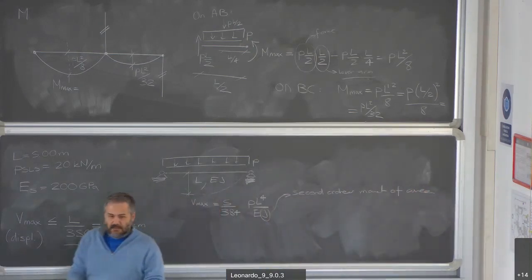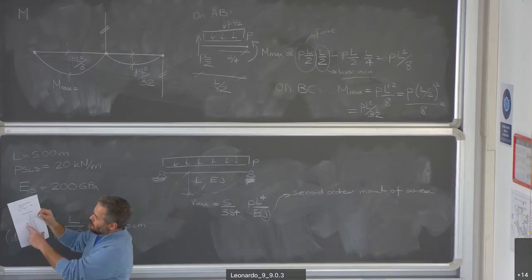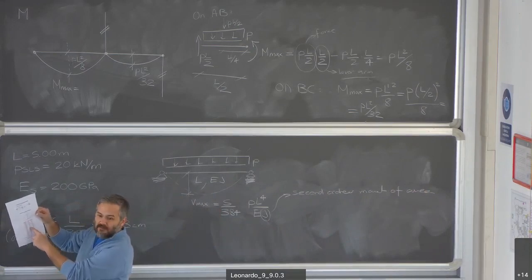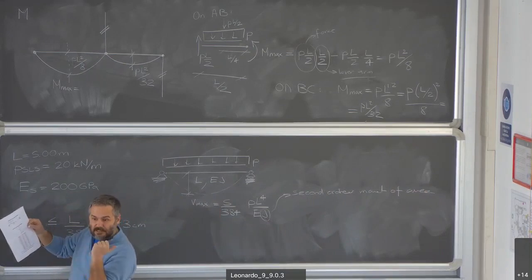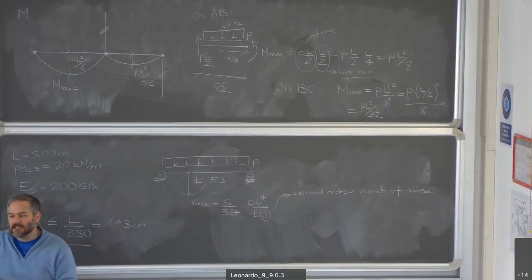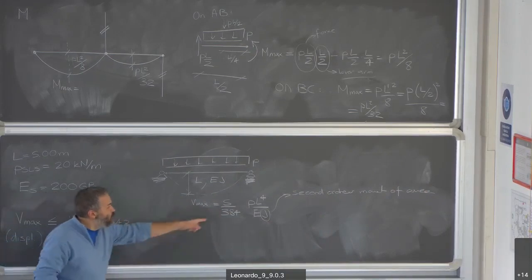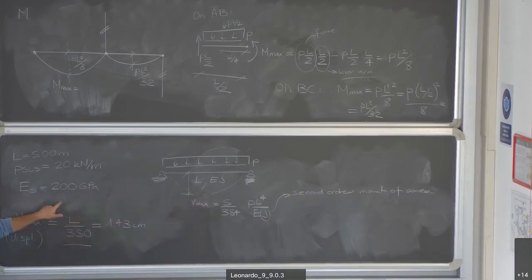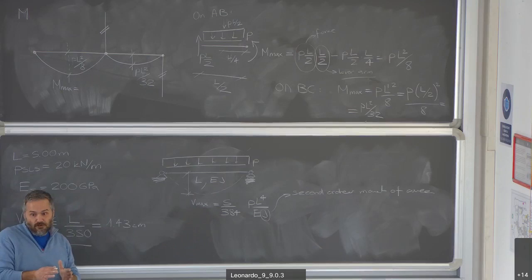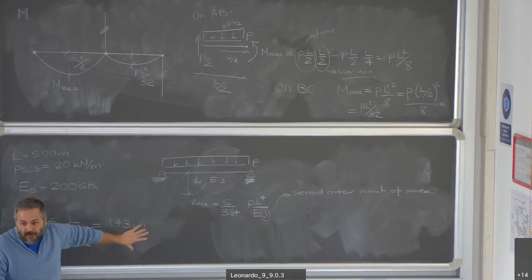When you pick a section, for all the different sections, you always have the info concerning, for example, the second order moment of area. So what will the design task be? Knowing this equation and this limiting condition, I will work out the minimum second order moment of area I need to fulfill the design task.